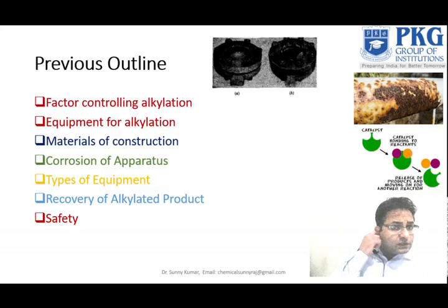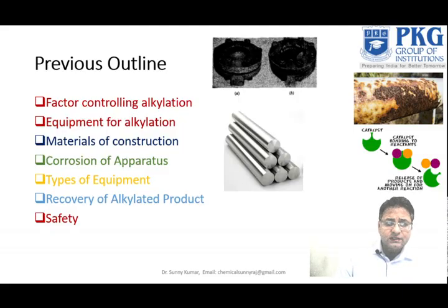And if you look here, this is before bursting. If the pressure is high, they can easily burst. This is after burst, and this is before burst. This can happen with the valves and the safety valve. The safety valve can break if the inside operating pressure is high. And this can happen due to corrosion, because the strength of the material decreases when it is in corroded form.